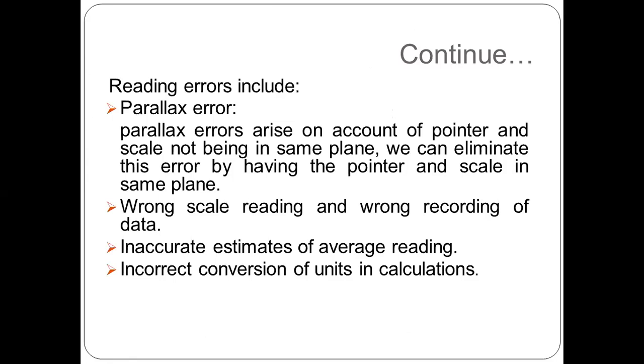The second one is parallax error. Parallax error arises on account of the pointer and the scale not being in the same plane. We can eliminate this error by having the pointer and the scale in the same plane. So this error, parallax error, occurs when the divisions on your scale are very small to visualize, and you are not properly matching that line with your particular product.